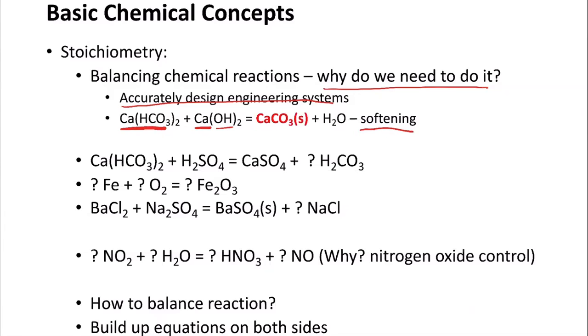Now let's think of this chemical process. We have this reactor here, and the water is being introduced into this tank here, and then this is the exit. At the same time, we add in this calcium hydroxide. Because there's sedimentation, we have solids at the bottom. But we cannot keep these solids infinitely long because they're going to build up, right?